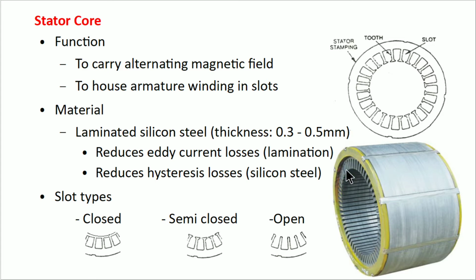When three-phase AC supply is connected to stator windings, a magnetic field is produced which is alternating in nature. Alternating field means the flux is changing always. The changing flux is linking with this iron core, and EMFs are induced in this core. Because it has a closed circuit, current starts flowing through this iron, which is not required in the motor action. These are called eddy currents.